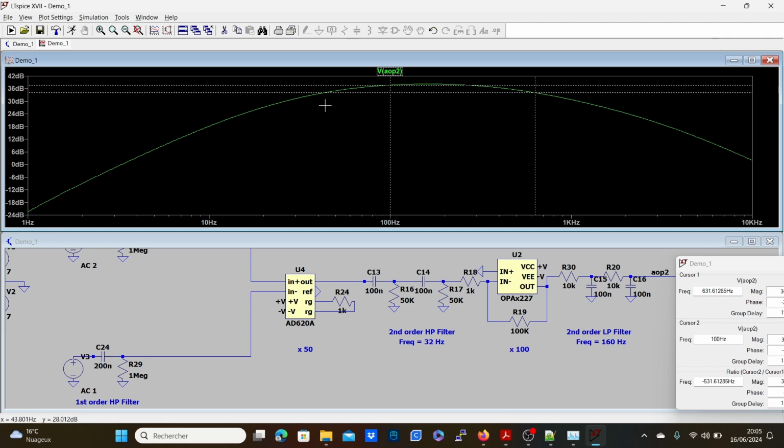You will not get a slope that's really, I mean, you can, if you lower the low pass filter, the slope is going to be a little more flat here like this, and you have a lower gain. And again, you have a lower gain, so you need to probably amplify it even more. Is that necessarily a necessity? You have all these things that you have to take into consideration, and at some point you have to stop simulating things and start testing it and see what it looks like. If the result you have is satisfying, you can stick to it and say, okay, I'm going to keep it like that. But it's a good thing to start from the simulation.